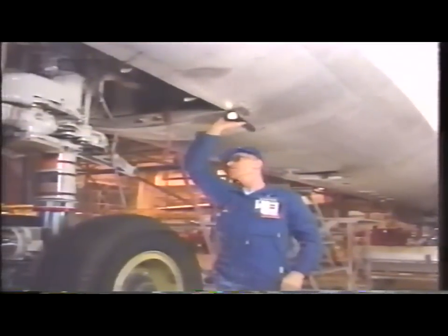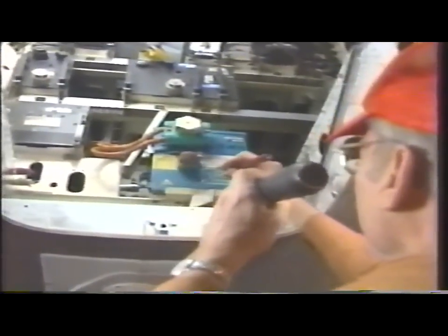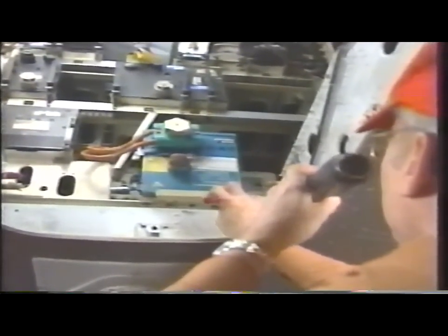The basic inspection tools mentioned earlier will help you find chipped, missing, and lifted paint, which could lead to corrosion of the metal underneath, dished and popped rivets, which means that the dissimilar metals have fallen victim to galvanic corrosion. Skin bulges or lifted surfaces, which mean that exfoliation or intergranular corrosion has begun, and cracks in the metal, which are a sign of stress corrosion cracking. Visual inspection, when done correctly, will help you detect the majority of corrosion types with a minimum of tools.